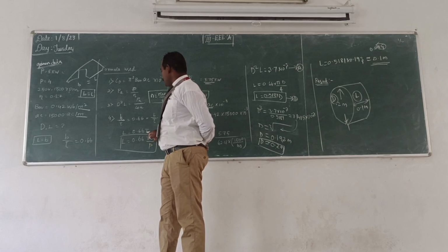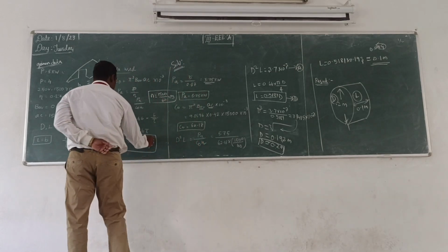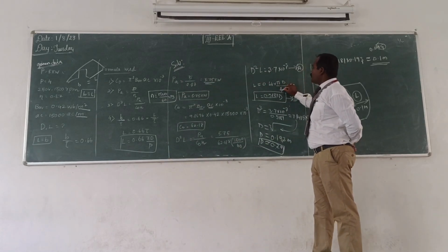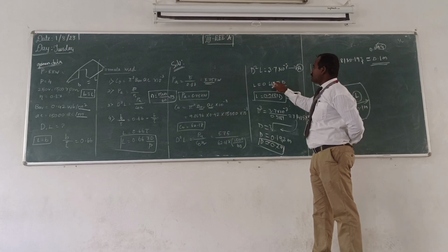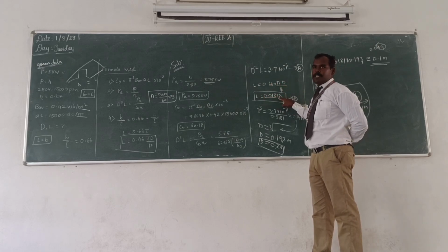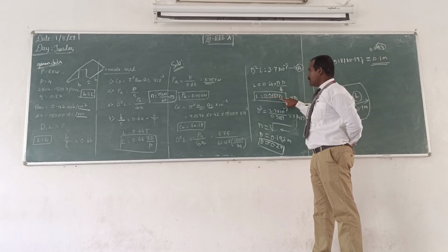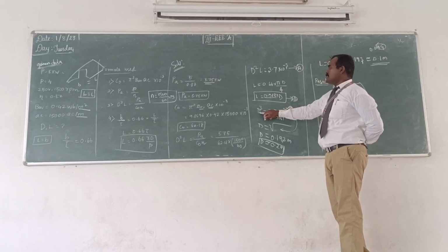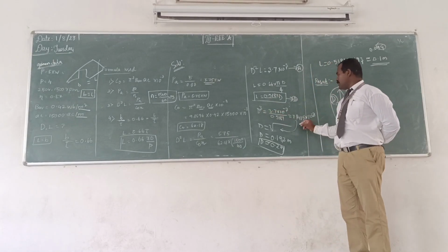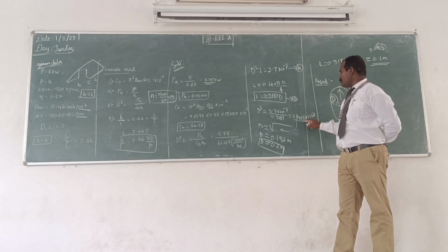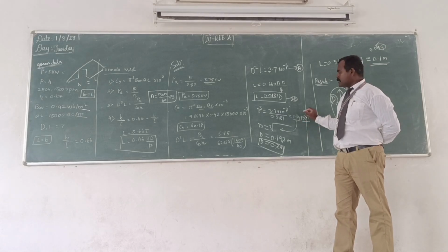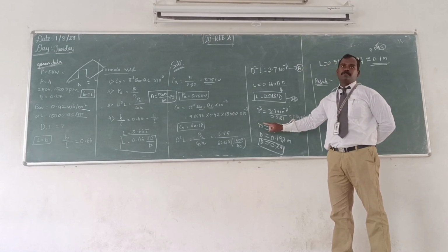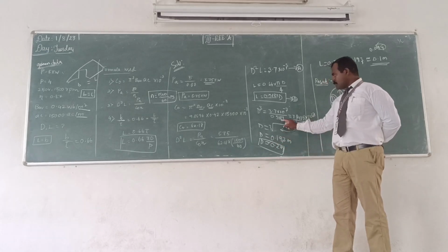The tau value we know from the formula, pi D by P. So we can substitute that value. Here everything is constant, and the number of poles is given in the problem itself. So you can substitute and find L in terms of D, right? Once we have found L in terms of D, we substitute this L value in the previous expression A, so you can easily find D cube. The D cube value we obtain is 7.1415 into 10 power minus 3. Taking the cube root of D cube, we can find the D value. D is the diameter of the machine.